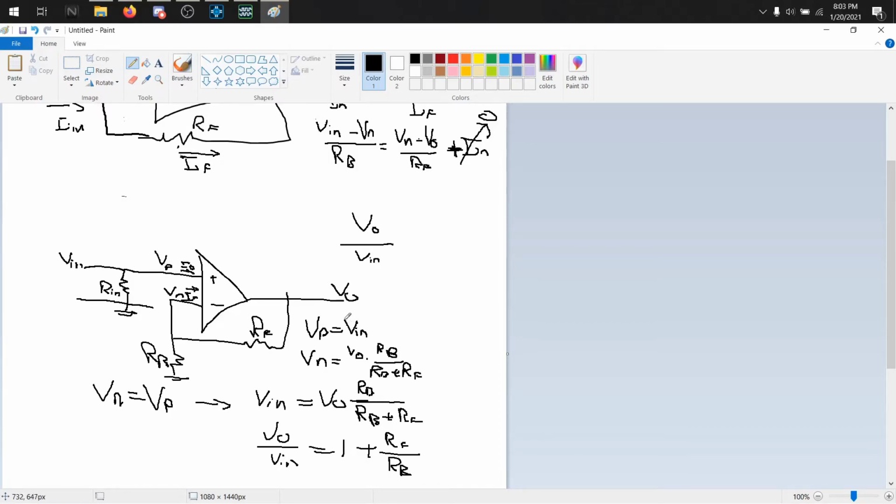All that the Rn resistor does is adjust your input impedance, because it'll be in parallel with an infinite impedance, so it'll just be Rn. So the input impedance into Vn would be just Rn. That's why it's there, but you don't need it necessarily. If it confuses you, you don't need it. I can get rid of it completely. I like keeping it in because when you do equations when they're not ideal, you want to have symmetry, and you can get hints from that too. Dr. Russell loves to do that.